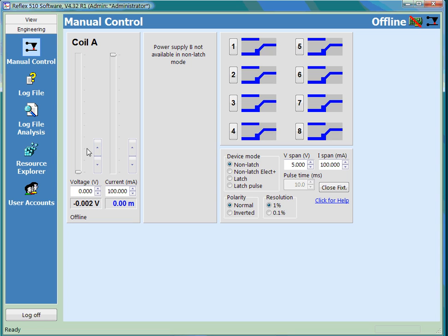You can do a little bit more though, because if you click on this up button, the slider is now moving by itself, and when it gets to the voltage at which the first contact state change occurs here, it stops, showing us the voltage at which that state change occurred. If we then repeatedly click on that up button, it advances through each of the contact state changes, stopping and showing us the voltage.